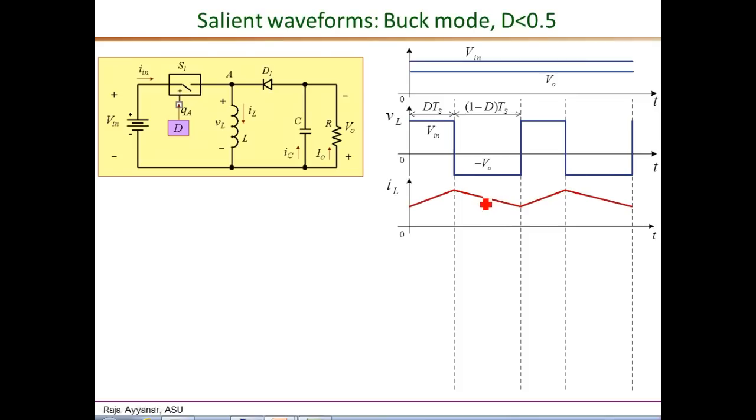So there is a family of curves corresponding to different initial conditions that is possible for a given inductor voltage waveform. The unique waveform that corresponds to the given operating condition is given by looking at the average current, for example. So the IL average, by looking at a KCL at this node, average KCL is equal to IS1 plus ID1, all average values.